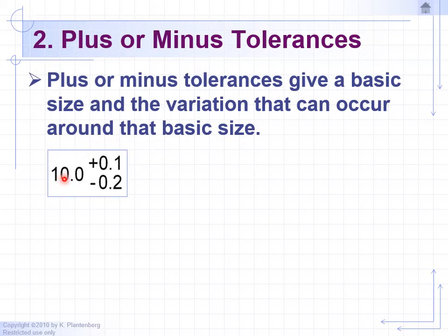So once again, this is providing the basic size of 10. This is the desired size. And the plus or minus, you're telling how much wiggle room you're giving the machine shop.